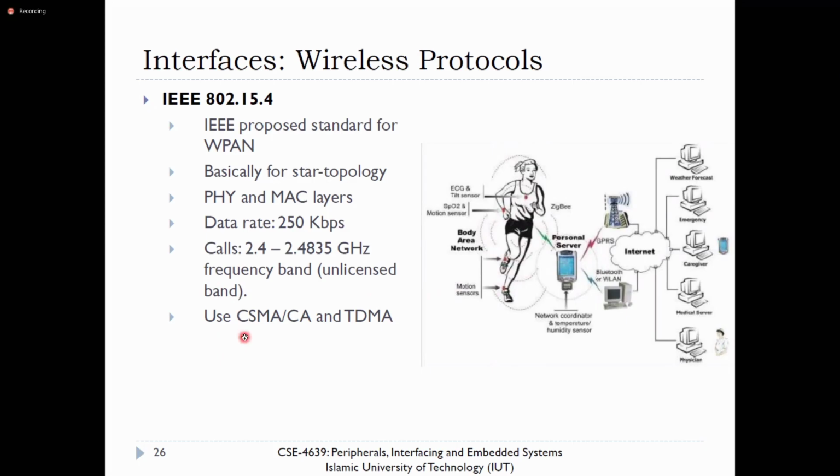I've just summarized the information about 802.15.4. The medium access technology supported by this standard is CSMA/CA, carrier sense multiple access, and also time division multiple access. So it is contention based and contention free. A hybridization of both contention based and contention free techniques is included in 802.15.4.